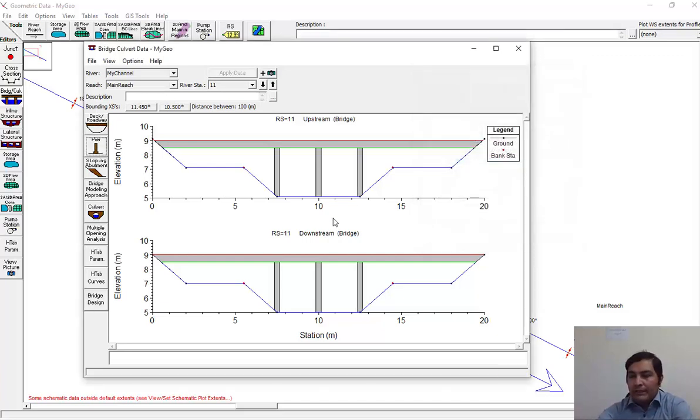Okay, I think this is a good shape of piers, and you can define new piers in this location or in this location or other locations you want. But I don't want to model a pier in this location. I want to use an abutment for this section and cover these parts. Okay, in HEC-RAS you can use a sloping abutment.